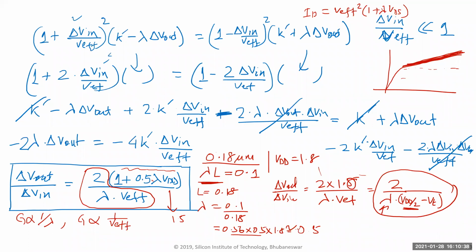But I'm going to show you later in the slide how, instead of using the saturation region, if you use the subthreshold region, then you're going to get the same amount of gain with a lot less current, if your speed is again not important. If you want the highest speed out of this technology, then you still go for saturation. If you're doing some kilohertz stuff and